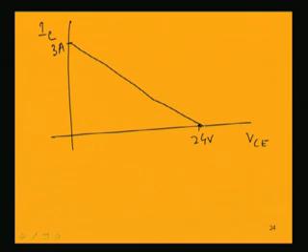And now, this is the maximum rated current for the power transistor, 3 ampere, and the maximum rated voltage 24 volt, and we have this point PD max at around the middle of the load line, because we have that point as 12 volt and 1.5 ampere, exactly at the middle of this load line we get the PD max.